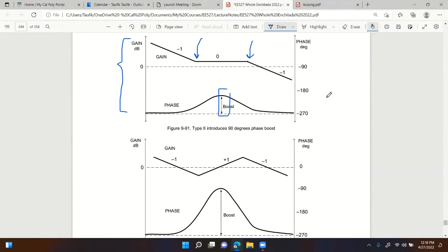If that's not enough, especially if you come across different cases, I'll go over those different cases later. Sometimes you need additional boost in the angles. In other words, 90 degrees may not be enough. You might want to have 180 degrees, phase boost, such as that. So how do you do that?